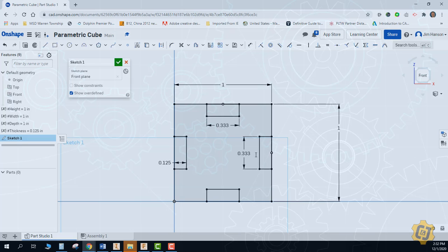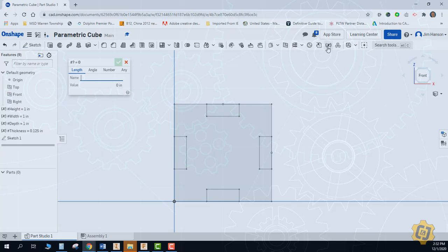Those may be a little bit too much. That doesn't really give me the surface area to be able to glue all this together. How about a happy medium of 1.5? How about that's something that I may not know what I really want yet? So I'm going to make that a variable. So I'm going to leave my sketch, go make one called, I don't know, divider.